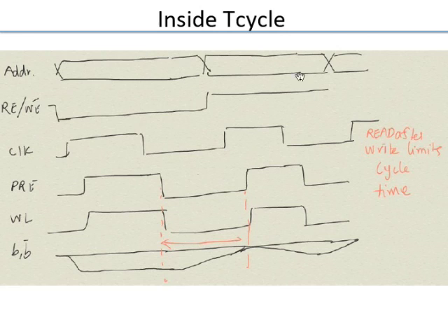Because when you do a write, the write enable bar is 0, so I'm doing a write. So after some time the precharge and the word line go high, so the bit lines are no longer held high, but then there's something, not shown out here, which is driving data onto the bit lines. There's a driver which, we said, is essentially just two NMOSes which drive either bit or bit bar down depending on the data value. Data is 1, bit bar is driven down to ground; data is 0, bit is driven down to ground, so that you put the right polarity of data into the cell.